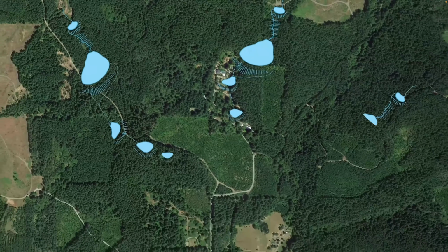You'll be looking at essentially proofing the data that you've already collected about your soil types from the NRCS or other soil resources. And so you'll be looking at the soil profile. You want to see what the conditions are of the different soil horizons. Though this really varies, you'll see that there are stratified layers within the horizons.